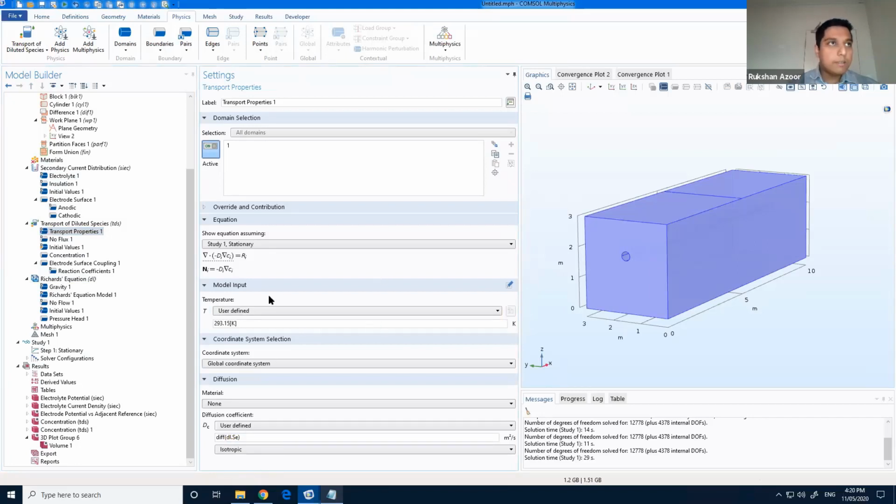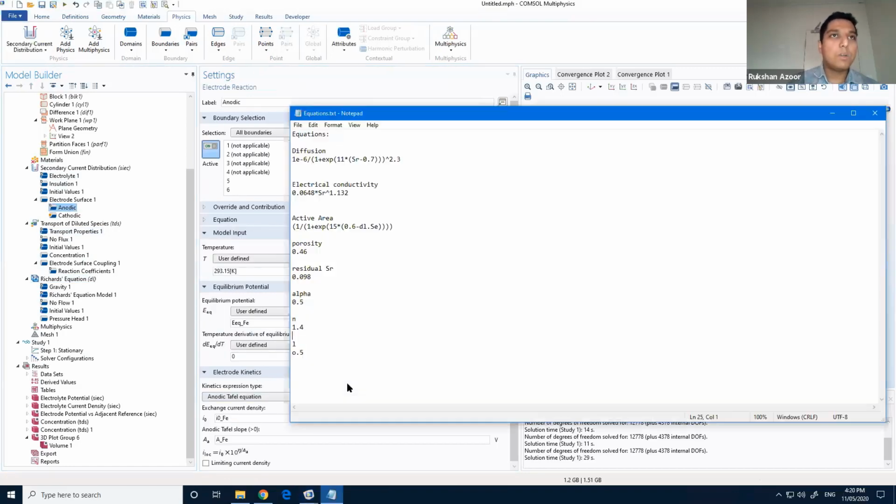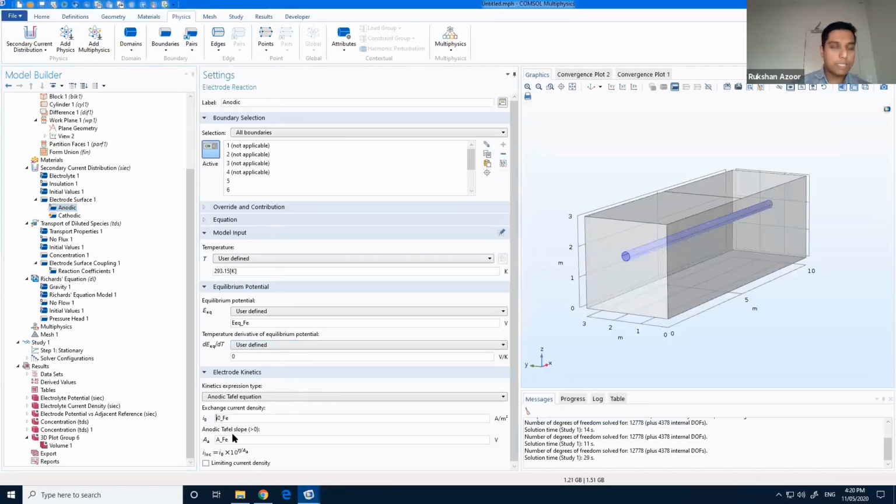Now, when we have different degrees of saturation, our anodic reaction also changes. It might not be relevant, but I'll have to put that through this term here. So I need a function that will depend on the saturation, so I need to put that there as well. So now we have a fully coupled stationary model, coupled between moisture flow, oxygen diffusion, and corrosion. Three types of physics coupled all together.